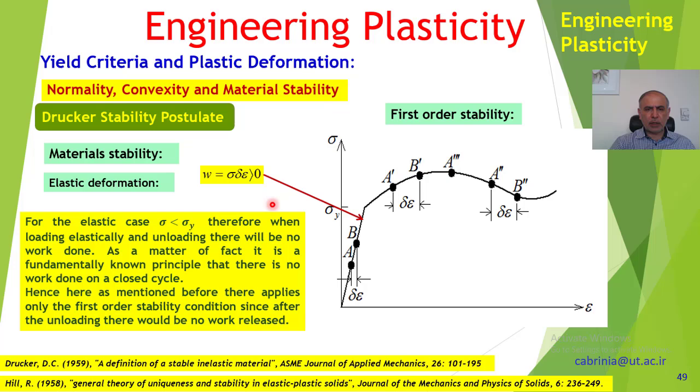and just delta epsilon times sigma. Okay, for the elastic case, sigma is less than sigma y. Therefore, when loading elastically and unloading, there will be no work done. It's a closed cycle. When we go up here and release the load, we go back.